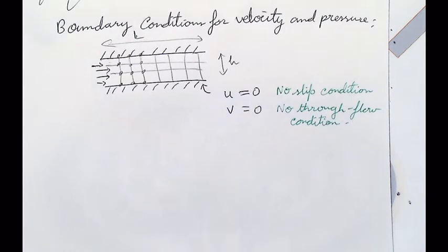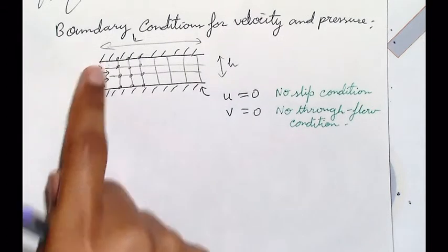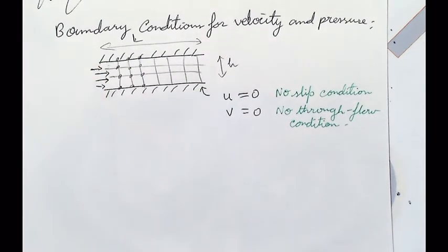So we need another boundary condition, left and right. Inflow and outflow boundary conditions. I haven't told you many things, right? What happens at the inflow, what happens at the outflow? I haven't told you what the mass flow rate should be or what the mean velocity should be. Without any of these, you cannot give me a solution.